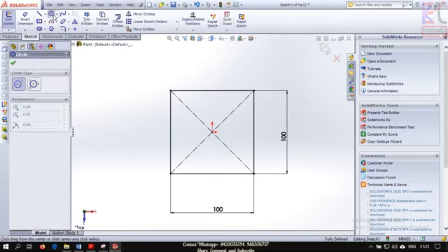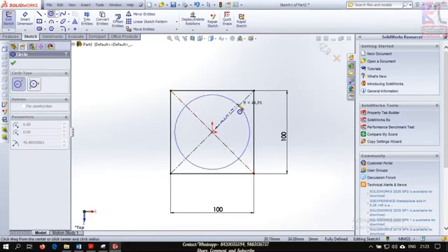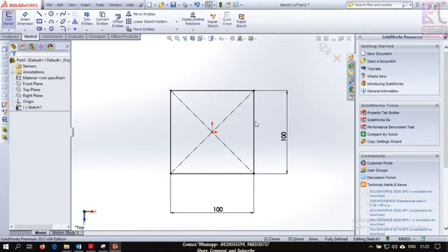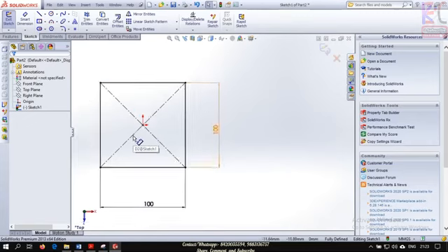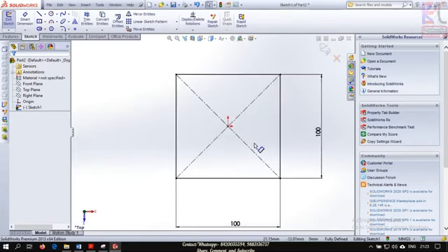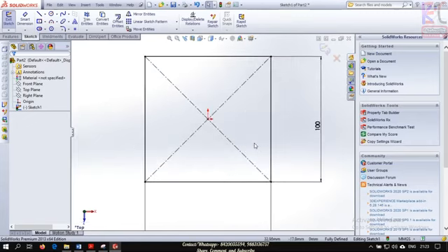So let me show you more things, like an array in AutoCAD, and its pattern over here. Let me draw a circle over here. I'll make a linear array or something. Before that, how to zoom? You just scroll up and down with the scroll key of your mouse.